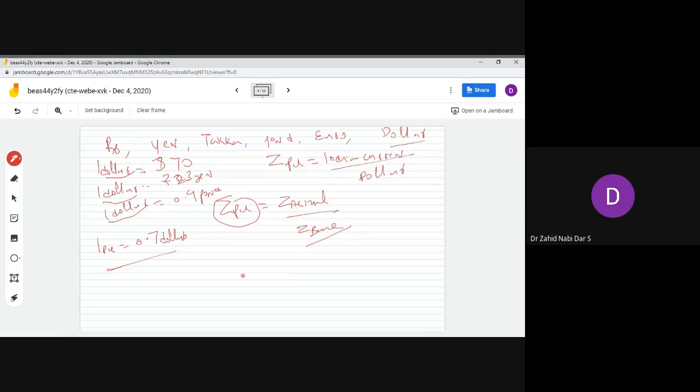We have different types of things available. We have a transformer, which will have a different impedance. We have a transmission line, which has a different impedance. So what we try is to get all the impedances in terms of one value. Suppose we consider the biggest value of the impedance and divide the actual value of all other terms by it, so it becomes easy to calculate.